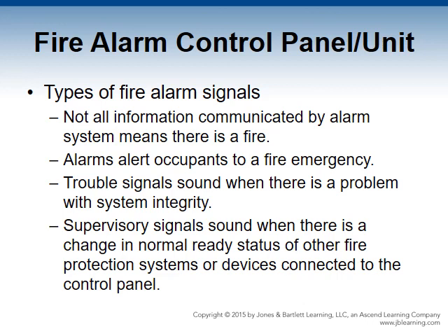The signal sounds once a manual or automatic initiation device operates. For example, a manual fire alarm box, smoke detector, or water flow switch. Horns, bells, and speakers may be used to sound a general alarm. In some situations, an alarm may sound only on a few floors or in a specific location. When the alarm sounds, occupants should respond immediately and evacuate the building.